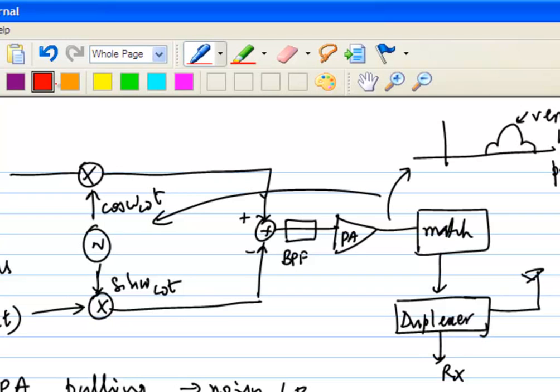This is the LO frequency, right? Typically, this will be several hundred millivolts. We looked at cases where there may be an active mixer. Remember, we talked about how you want to size it. At the end of the day, this is going to have a fixed amplitude, irrespective of whether you generate it as omega 1 plus omega 2 or otherwise. And typically, the VCOs which you design will also have a fixed amplitude. They'll be similar. To minimize noise, you tend to have maximum amplitude coming out of the VCO. So the amplitude itself will not matter too much. As long as the frequencies are offset far enough, it won't pull anymore.